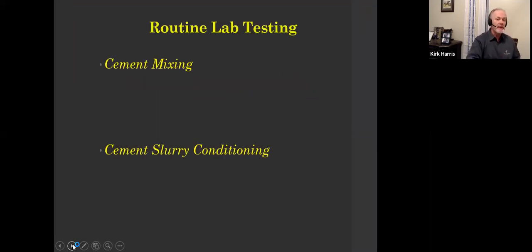We're going to talk about cement mixing. We're going to talk about conditioning the slurry, bringing it to the right temperature, sometimes temperature and pressure. What are those 6 routine lab tests that we do every day? What are they? We do 3 just after we mix the cement. We do 3 after we condition the cement. Although for any test, you can condition the slurry, I suppose. Name those for me while I sip my coffee.